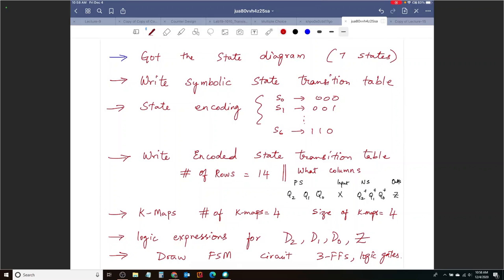But what becomes crucial in finite state machine design is to take a look at the problem statement, state the assumptions clearly, and then go to the state diagram. So that happens to be the most, that's what tests your creativity, and you need to think about that a little bit more carefully. But after you get to the state diagram, the process is very structured. It's one step after the other. There's not much that can go wrong if you just follow the rules.